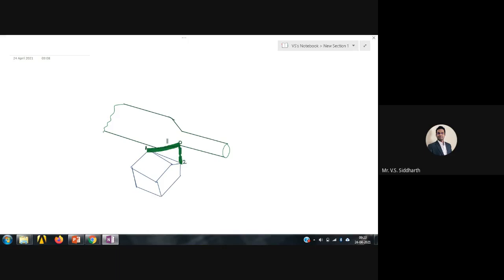But with the workpiece, only some part of this side cutting edge, up to this point, is coming in contact. This 0 point is obviously coming in contact, but apart from that, only the 01 part up to this green highlighted part is coming in contact with the workpiece. Then why should we call this 02 one of the cutting edges when it is not at all contributing in any of the cutting, or when it is not at all coming in contact with the workpiece?